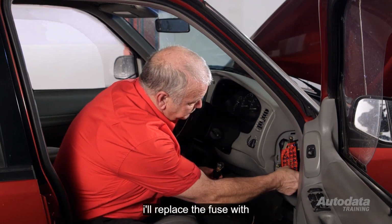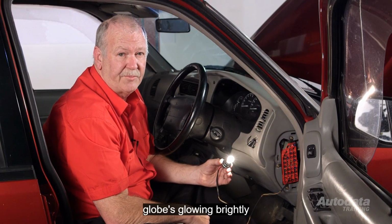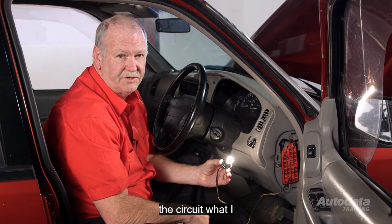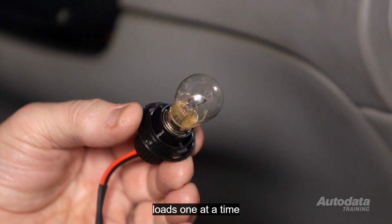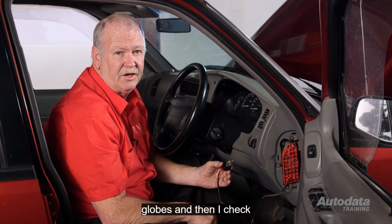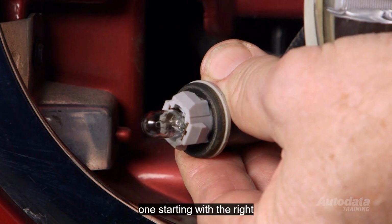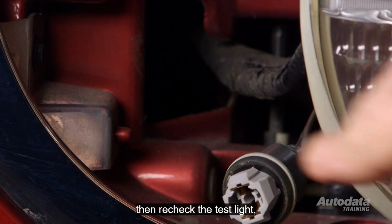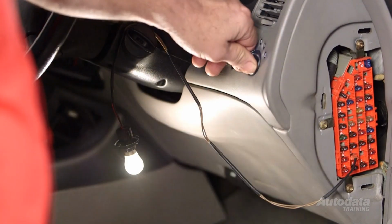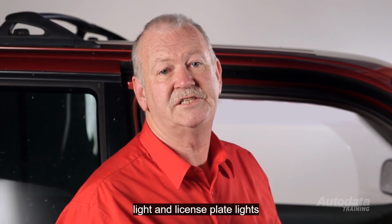I'll replace the fuse with my test lamp and turn on the parking lights. As you can see, the globe's glowing brightly. That indicates a short in the circuit. What I have to do next is remove each of the loads, one at a time. In this case, it will be the light globes. And then I check the test light between each one. Starting with the right-hand front park light, I'll remove the globe and then recheck the test light. The light is still bright, so I'll move on to the right-hand rear tail light and license plate lights.